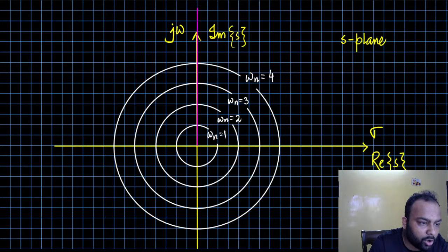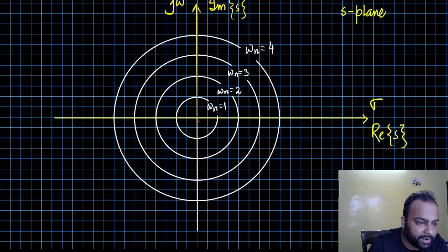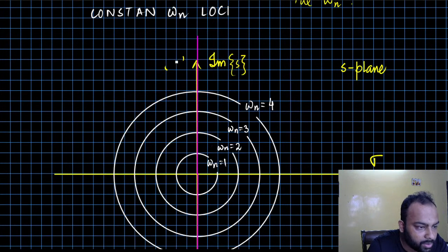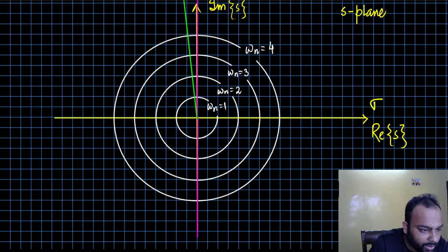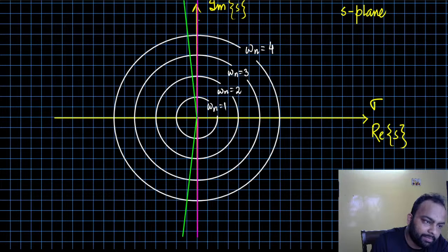So now let's draw the constant damping ratio loci. Pole pairs on this would have 0 damping ratio. Pole pairs on this, of course, we would have more circles actually. The number of circles is kind of small, at least for what we have chosen. Anyway, it doesn't matter really. You understand the point, right? These lines are just there as grids. Poles can be in between any of these.